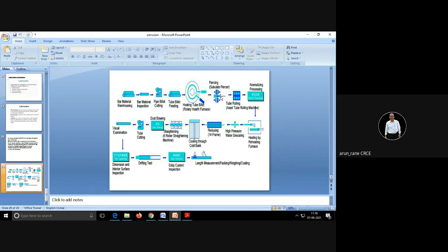So this is what is your push extrusion. So the rod is passing. Okay, either the feed is given to the rod or the feed is given to the billet, which is passing between the two rollers. Generally the feed is given to this component. ये जो rod है उसको stationary रखते हैं so that the hollow will be created. So even the outside and inside can be done simultaneously, right? Can be done simultaneously.